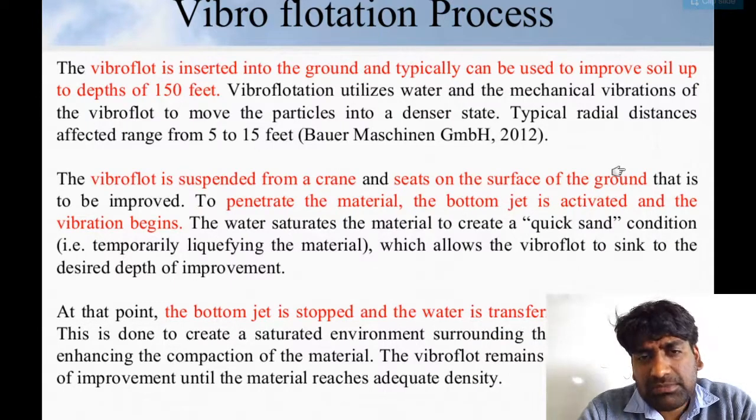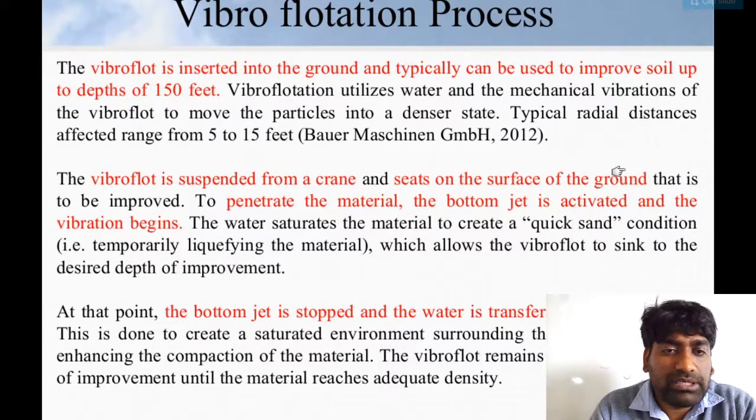At that point, the bottom jet is stopped and the water is transferred to the upper jet. This is done to create a saturated environment surrounding the vibrofloat, thereby enhancing the compaction of the material. The vibrofloat remains at the desired depth of improvement until the material reaches the adequate density.